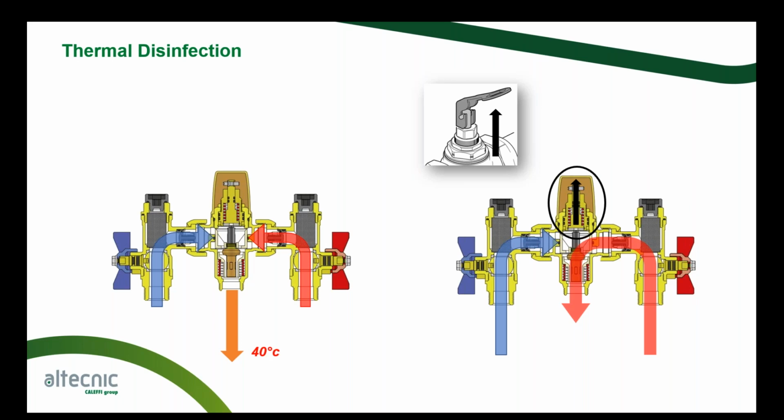We're taking the bacterial growth out of that mixed pipe work. We're killing it off at high temperatures all the way through to the outlet. So we're making sure that we're removing that bacterial growth by thermal disinfection all the way to the outlet, and not leaving a potentially dangerous dead leg within the areas itself. So again, like I say, it's pulling 65 degrees through the sensor, and then 65 degrees out of the tap itself.